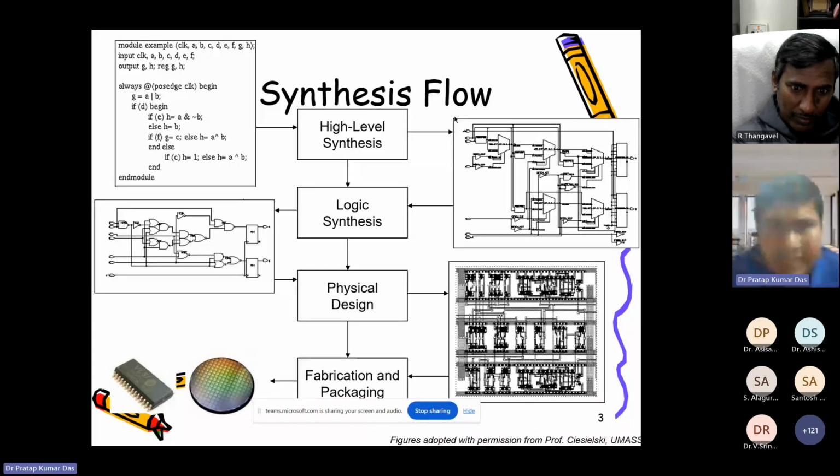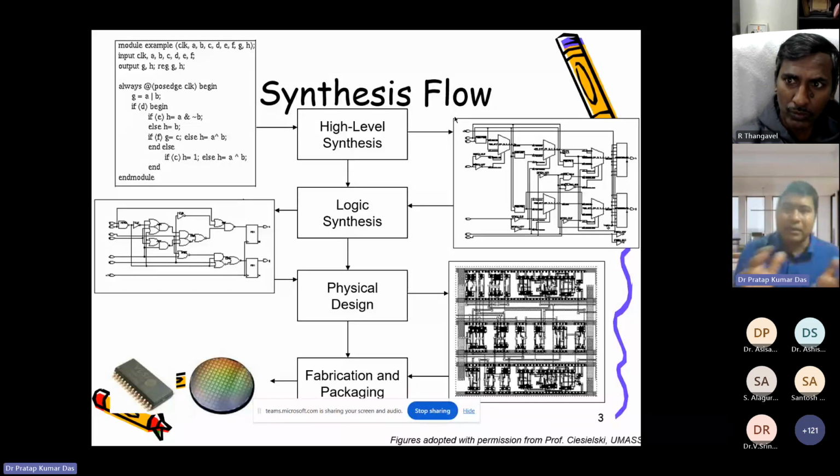So basically, synthesis is nothing but, let's start from an example. When we are building a chip, first it will be at an abstract level what that chip needs to do. So the marketing team will tell the design team that we need so and so features, so many reads, so many writes, so many multiplication functions. From that, the hardware will be prepared with the block diagram, right? What are the functionalities? After that, the functionalities are written in a system level language like SystemVerilog or Verilog, and that gets into synthesis. By synthesis, it will map into some feasible blocks.